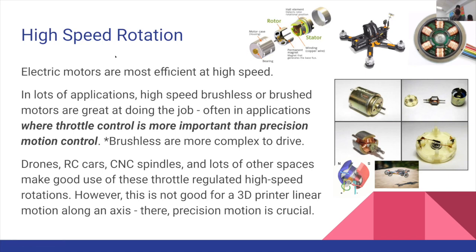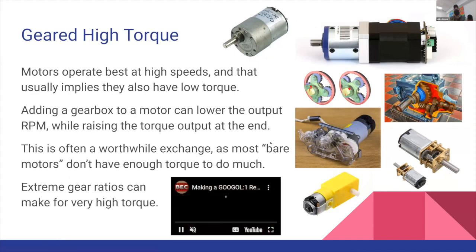But when you're doing this, ultimately, with this motor, you're not going to be able to finely control it like a stepper, but you can control how fast it spins with a fair amount of precision. So you could say, I want 16,000 RPMs, and that is something you could control, but it would be much harder to say, I'd like you to make 1/4 of a rotation, because the commutator just doesn't let you get that precise. So those are all interesting features.